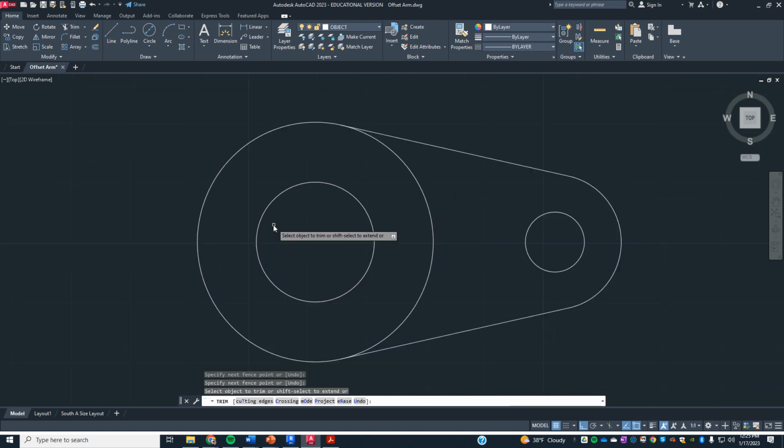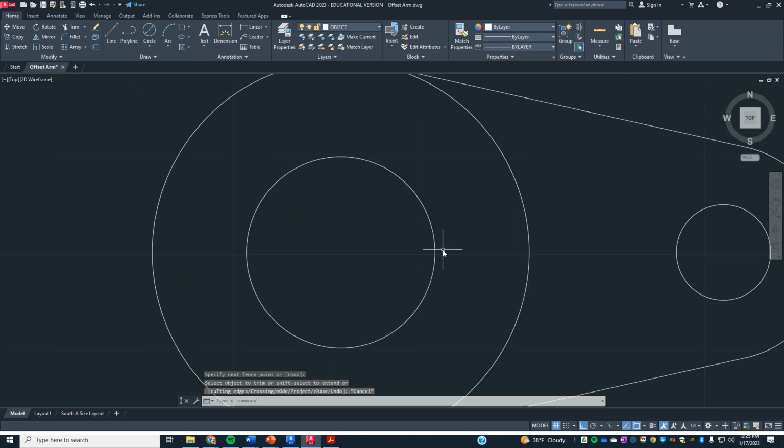Okay, and now we have our keyways in the middle, starting from the quadrant. We'll do the one on the side here first. This one starts from the quadrant. It comes out 3/16 of an inch. It comes over 1/4 of an inch, and then we're going to drag it down. I'm going to do the same thing going this way. I'm going to come back 1/4 of an inch, and I'm going to drag it down. We'll do the trim command. So we're going to trim all this out, and I accidentally did too much there. Not a big deal. I'll just take this and drag that way. And we need to do some more trim command and trim this out as well.